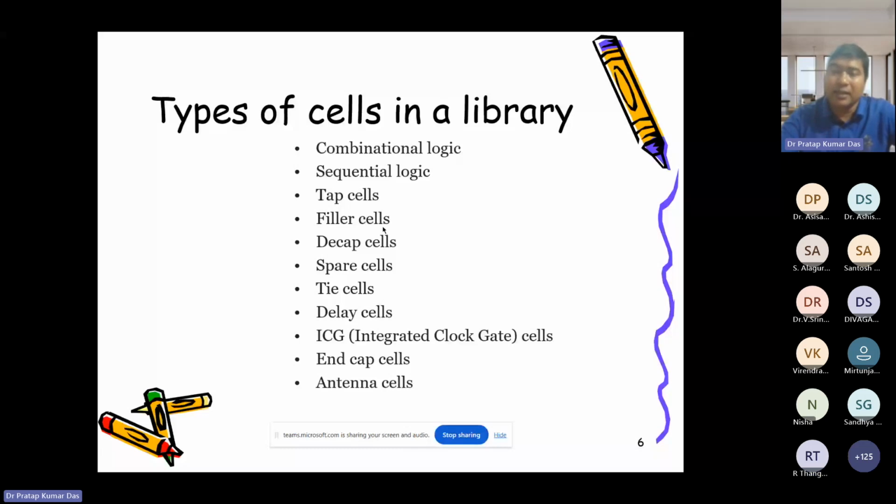where there is no clock, the output is a function of only the input. That is called combinational. Whereas sequential is output as a function of the input and present state. Cascading is not sequential. Output depends not only upon the present input but also the past output. That past output will be stored in a memory. Those memory elements are called flip-flops, and that particular unit is sequential logic.